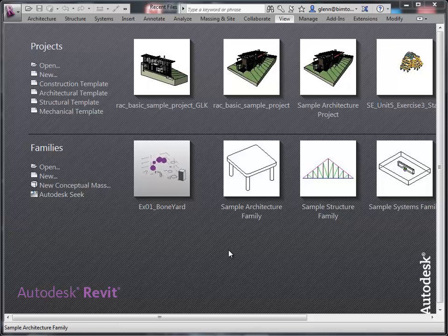Okay, let's get going and think about creating a brand new Revit file. When you open up Revit and you're ready to start creating something new, you have on the main splash screen a choice of open or new or some of these different things. We're going to open new, and we're also going to open the architectural template. If you're working on one of the workstations where it's already installed, you'll say new, and we'll get that same choice.